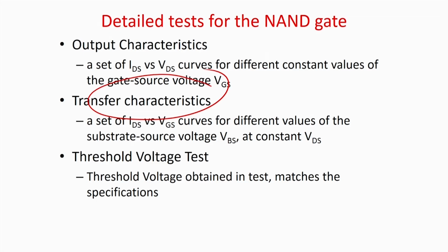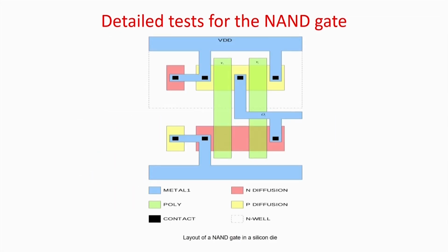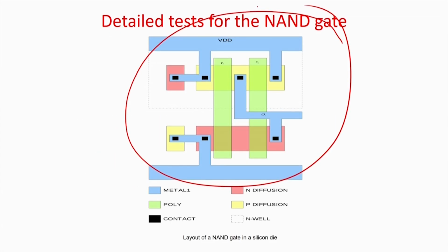So I can do all those tests, and not only that, this is actually the final layout of this circuit. You can even start looking at the layout from the physics point of view, whether this line or this width of the copper implant is fine or not, whether the vias are fine or not. You can use a microscope, or there are things called probers, and you can even open up the chip, look through a high powered microscope and see whether all the parts of the layout have been done properly or not.